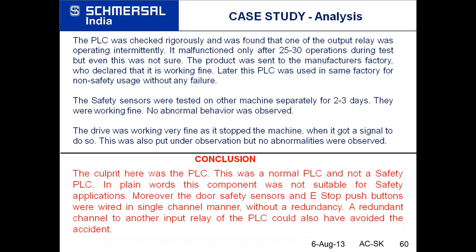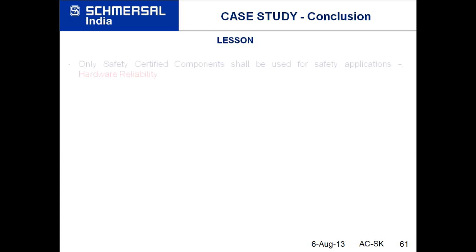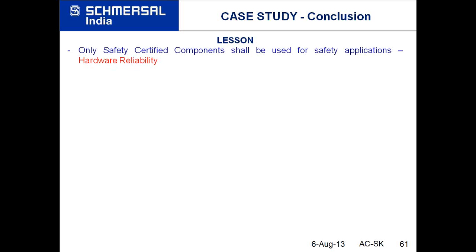Okay, so the PLC was the culprit because it was not a proven component. A normal PLC was being used for safety applications. So what should be our lesson from this case study? The first lesson: only safety certified components shall be used for safety applications so that we can achieve hardware reliability.